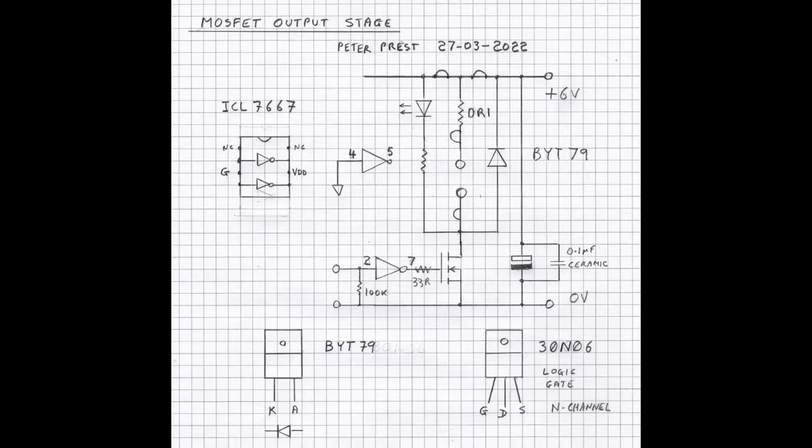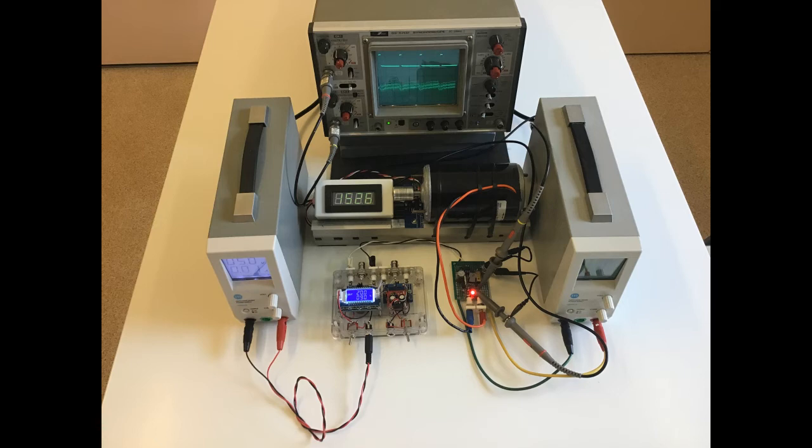For this test, the current is monitored by observing the voltage drop across a 0.1 ohm series resistance. Unfortunately, this low-level signal suffers from some 50 Hz pickup. Since the measurements are referenced to the positive supply, the current would be shown upside down. But the oscilloscope channel 2 allows inversion. Channel 1 cannot be inverted, so the voltage signal is shown upside down.